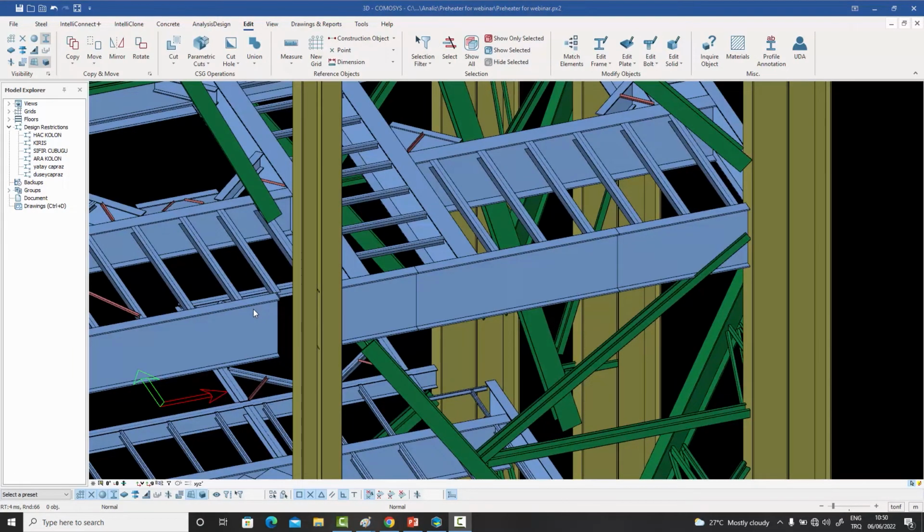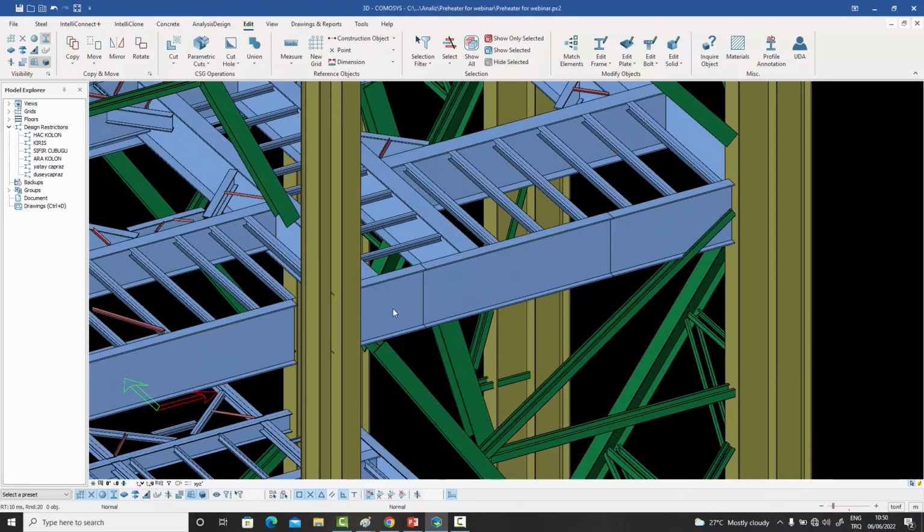So now let's start with the buckling length calculations of elements, as that is a very problematic area in most programs. If you input your structure according to the detailing requirements, the programs really mess up when they have to calculate the buckling lengths. So over here, I've divided this physical beam into 3 parts because I want splices over here in the detailed model.